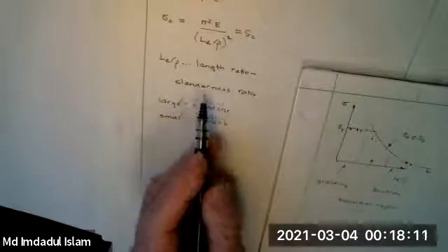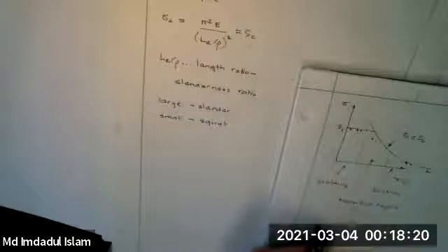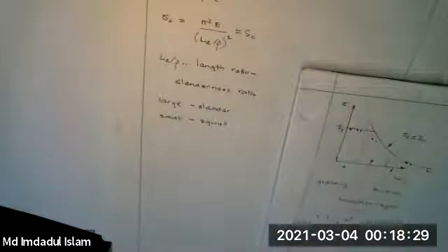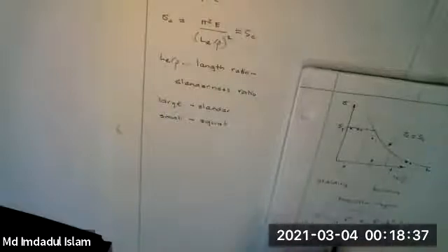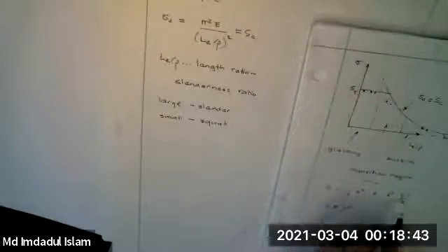Yeah, if you had a square beam, could you do something similar? Oh, yes. You can, like in fluids where you use hydraulic diameter. You can get a radius of gyration for a square beam. So, a square beam, let's say B equals H, and the area is B squared. So rho equals B over the square root of 12.